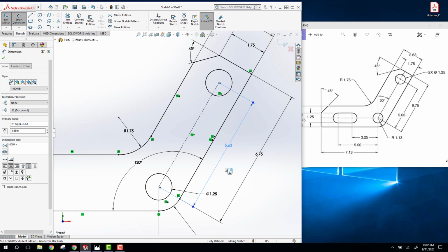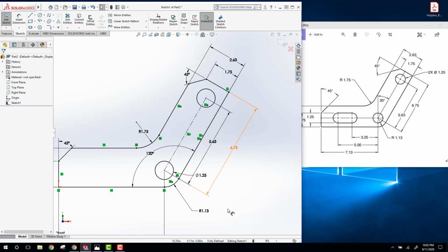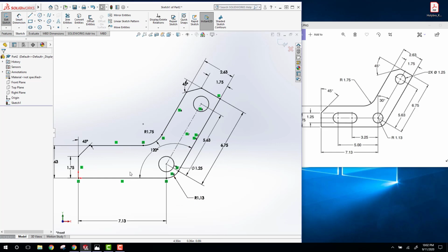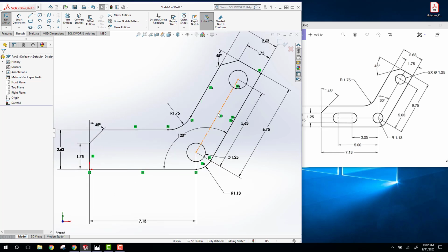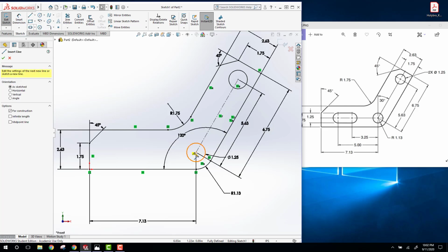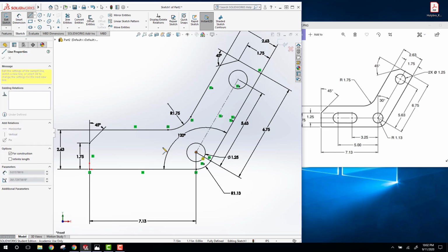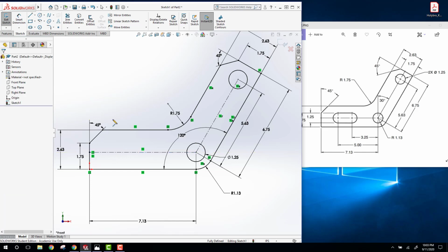All right, so again, we check down where our sketch is. Now our sketch is fully defined. So we need one more thing. So again, I'm going to use this new tool that I just showed you about, this center line. So I'll go here and I'll click on center line, and I'll click here. I'll drag across, and I'm going to let the horizontal constraint be put on. And now you see that the horizontal constraint is there plus the coincident constraint because I'm touching this line. So I'll click, and again hit the escape key to turn that off.